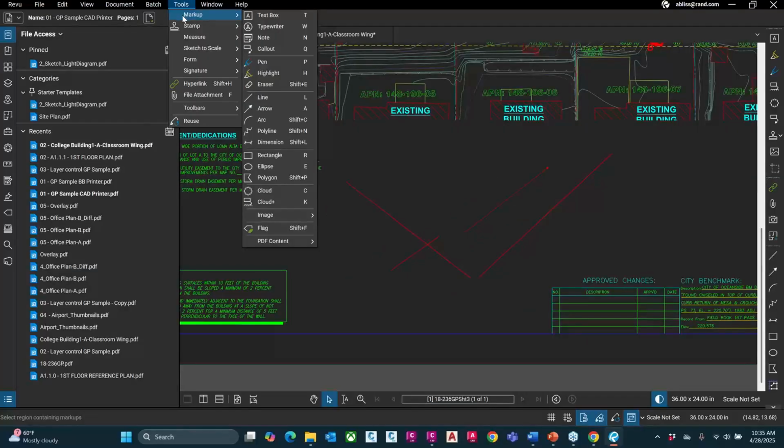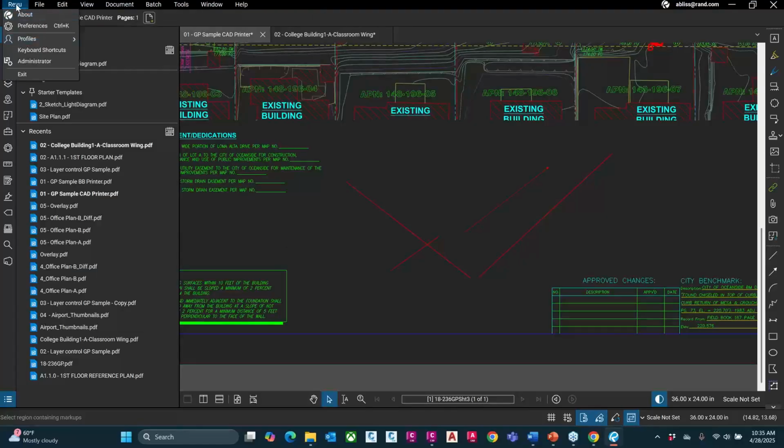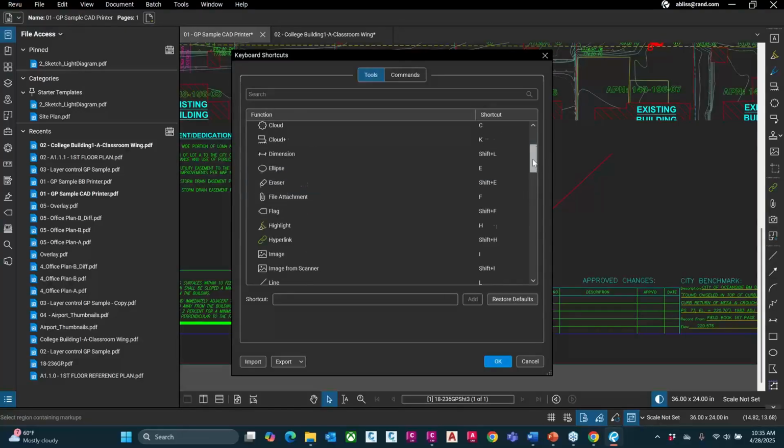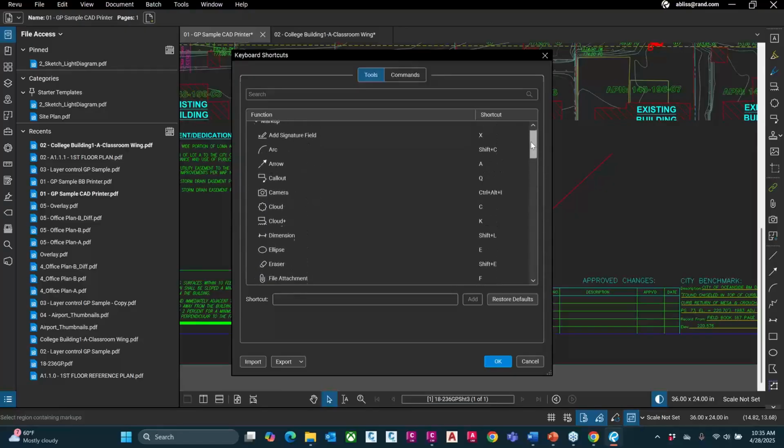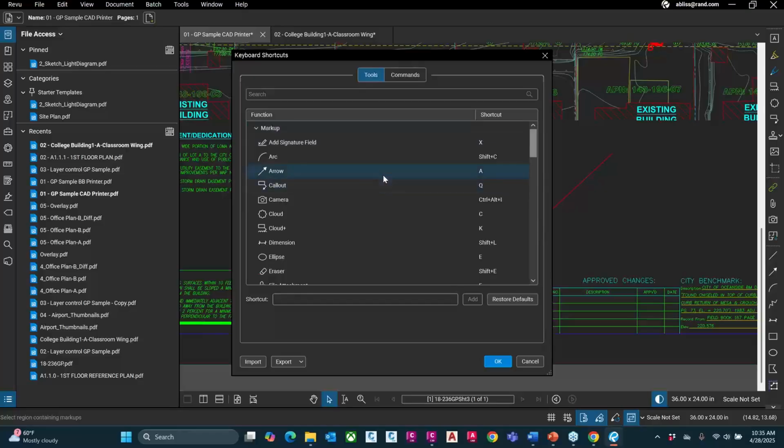A lot of us know that alias edit tool, that's the command in AutoCAD, where you can change the aliases around. We have that ability as well here in Bluebeam. You go to your review drop down flyout, keyboard shortcuts, you can click on that. Here's the list. And if you wanted to change anything, such as you want arc to be A and not arrow, you just go right there, reassign it. Click on arc, put A. It'll let you know that's already assigned to arrow, and you can be fine with that. You hit reassign, hit OK.